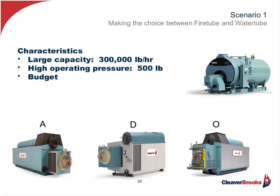The next thing that would favor a water tube as opposed to a fire tube in this particular scenario is the large capacity. In this particular case, 300,000 pounds per hour that I need for my process. And I'm going to be operating at pressures up to 500 pounds. Now, if you take a look at 300,000 pounds, that's about 7,800 horsepower. A fire tube is limited to about 2,200 to 2,500 horsepower as a package. These boilers go way up well over that. And we could be talking megawatts with water tube boilers.